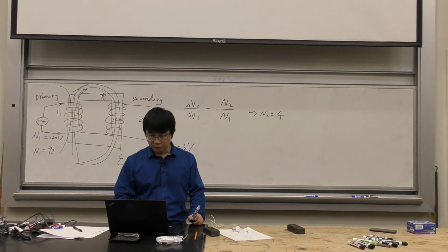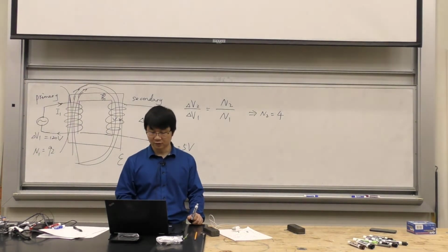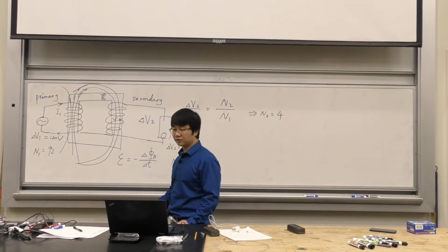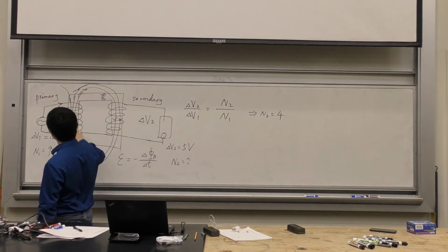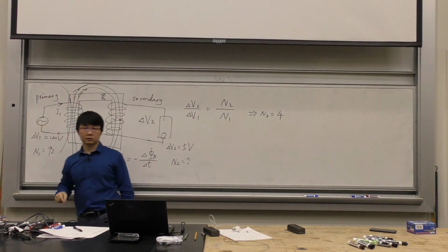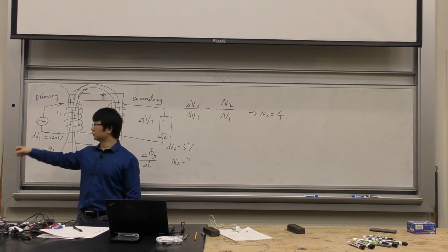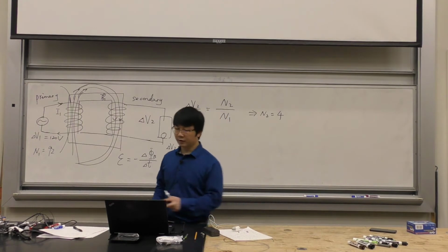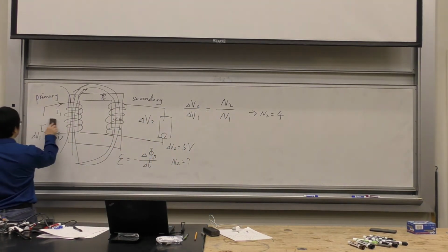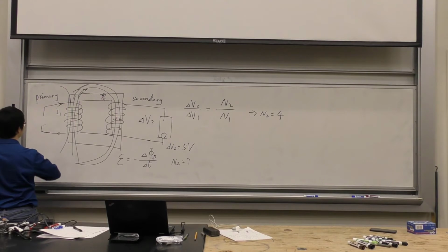Now the next question, okay, this is something I want you to think about, okay? But if you notice what I said at the beginning, you already know the answer and you know the reason. If the primary of a transformer is connected to a battery, so say I have a transformer, okay? And I connect it to a battery instead of the wall outlet, because the wall outlets are all AC circuits. If I connect this to a battery, okay, can the voltage still be changed? Say I connect this to a battery with like 3 volts.